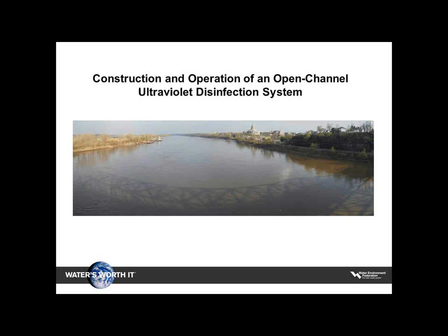Well, thanks so much, Paul. Before I turn it over, I can't help but step in here and interject real quickly because there's several questions that have popped up on dose. I want to make sure that the doses we've been talking about for these first two presentations today are actually tied to a bioassay surrogate organism, and usually the reference is MS2, and due to some pretty substantial changes in the UV industry, that's kind of in flux right now if that's the best dose.